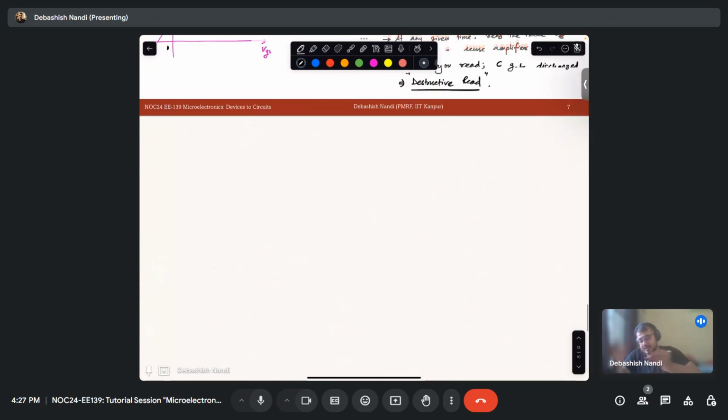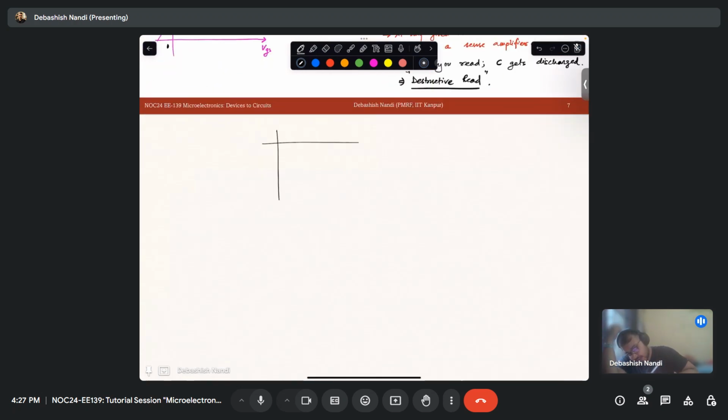So what does a leaky transistor mean? For example, let's say this is your word line, this is your bit line, and you have something connected to this. Suppose you make your WL equal to 0. Okay. Transistor should be ideally off. But then again, I off is flowing through this transistor, should be off, but non-zero I off is flowing through this transistor, right?